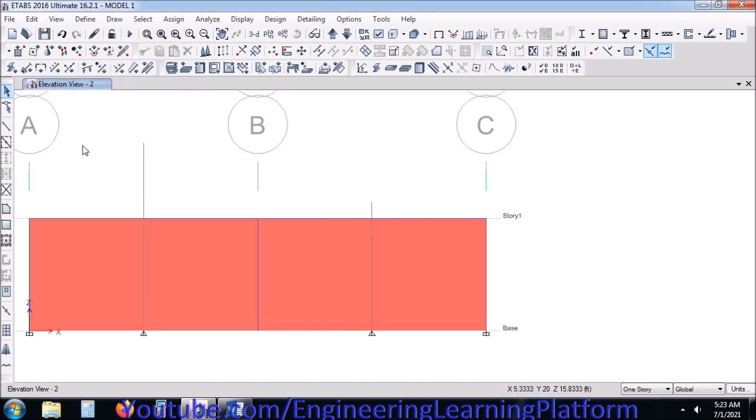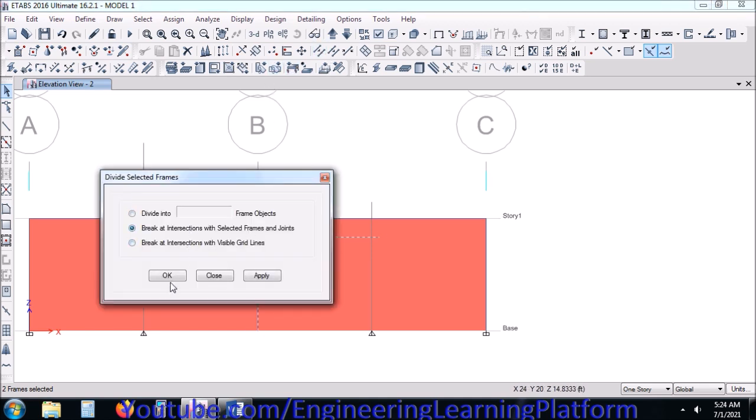So I've divided the line segment into 5 segments, so that we'll be able to draw the opening inside the wall. Since it was a 10-foot line, I divided it into 5 segments, so each segment is 2 feet, as I needed a 2 feet distance from the top. So that's how I snapped there and made the mesh in the slab for the opening.